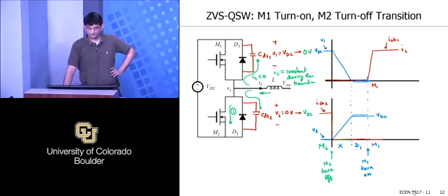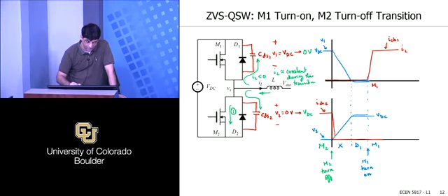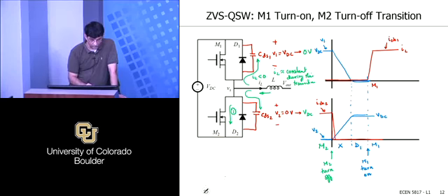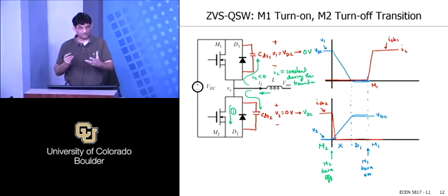Will there be any small power loss because of the diode conducting? Yeah, so there will be some small diode loss there, and if you wanted to be really accurate, this would not come down like that, it would actually come down like that, and the voltage waveform here would actually have this quadratic period and then the linear rise period, right? The same thing we did earlier. I did it much more carefully.